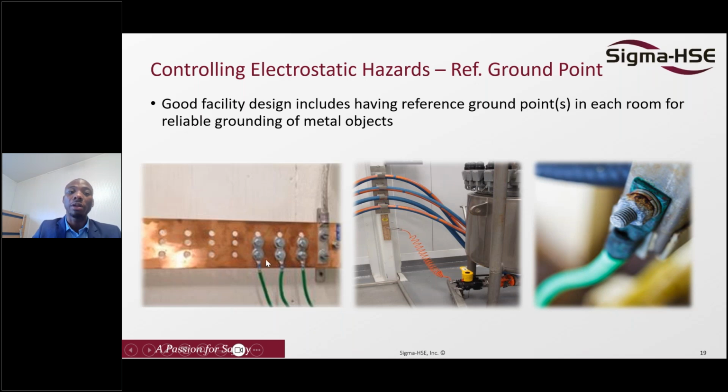So you connect your various equipment to this bus bar, and the equipment will automatically be bonded and grounded. That is something that facilities can do. Or, on the far right, you can connect the equipment directly to the ground itself to ensure that the equipment is grounded.